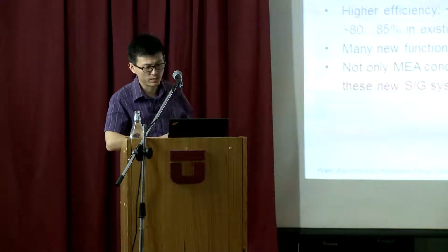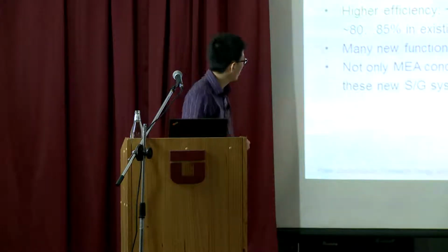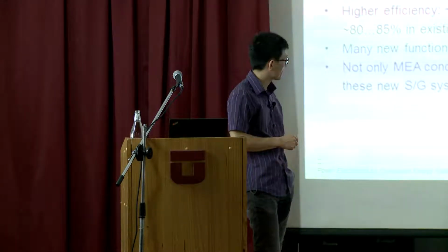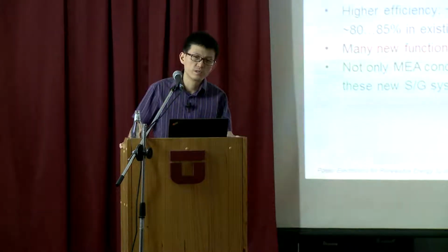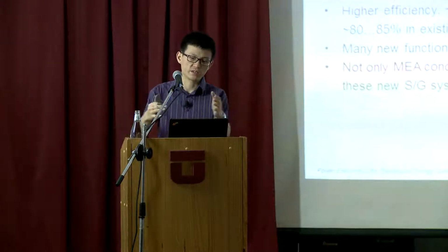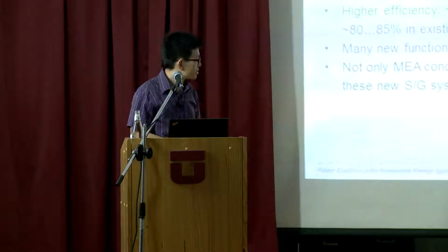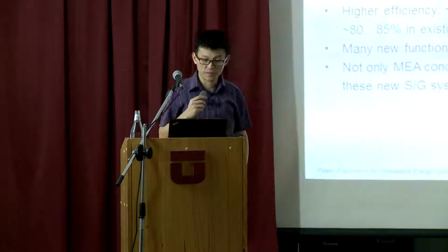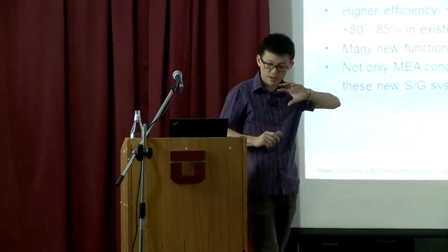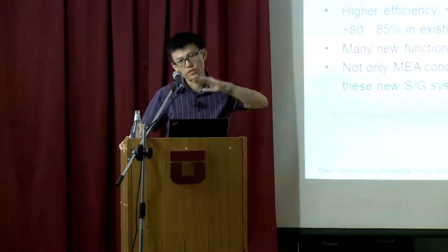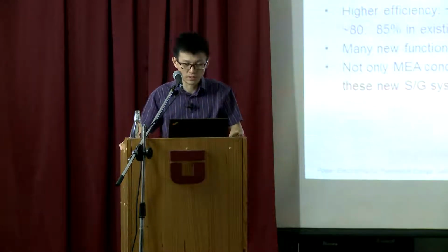Efficiency-wise, about 10% improvement compared with current technology in onboard aircraft. The current technology of this generation system in the aircraft is a kind of 3-stage generator. So you have 3 generators connected in series, and they have dials rotating with the shaft. This is why it's not very efficient, and also heavy, because it cannot rotate very fast, because the hydraulics rotate with the shaft. In that case, you cannot have very high power density in the system.